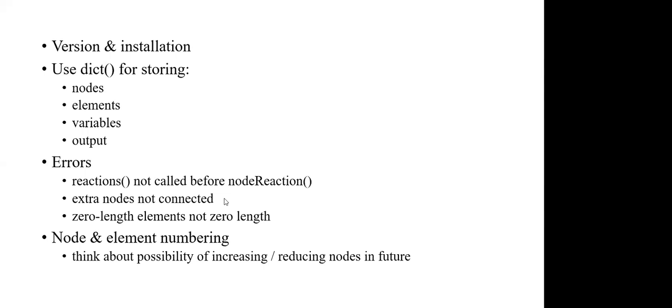So you need to make sure, especially when you have a lot of nodes, a very big model, that you know where your nodes are and what you are doing very clearly, because sometimes you might not be able to visualize every single detail. Just take note of that.